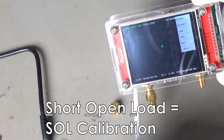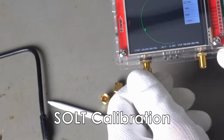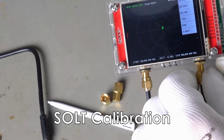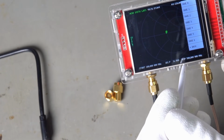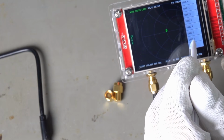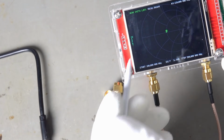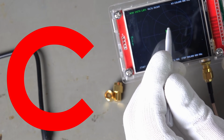This is called SOL calibration. If we connect both ports and tip through, we get a SOLT calibration. Now we can save it in one of the 7 memories. Here the instrument shows us if it is calibrated. Without this capital C, it is uncalibrated.